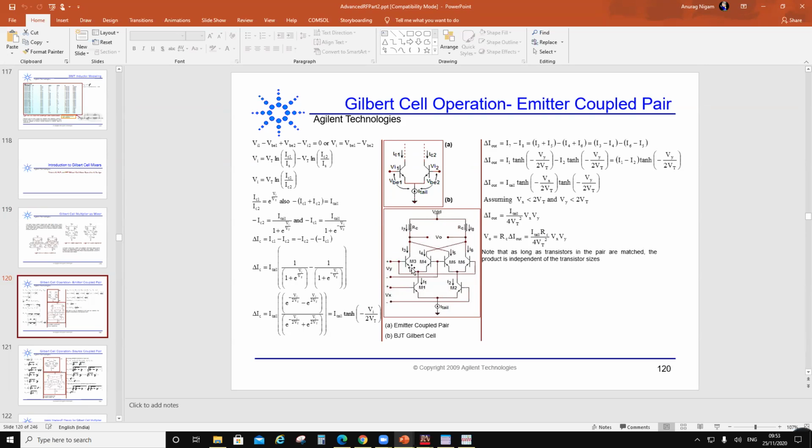So there are basically 3 translinear cells. What you call this is a translinear cell. Two at the top and two at the bottom. The two at the bottom are steering the current and controlling the GM of these devices, M3, M4, M5, M6.